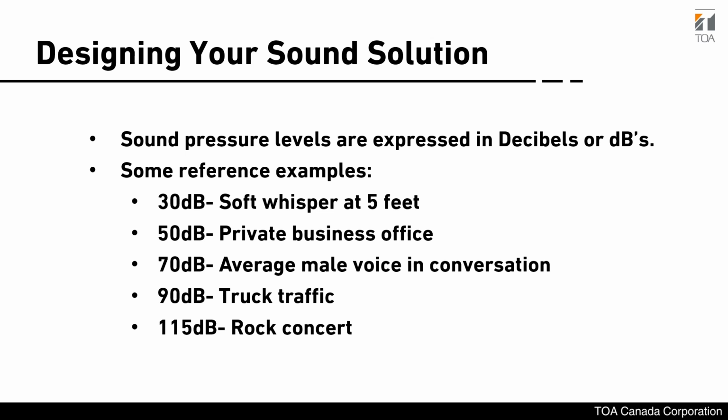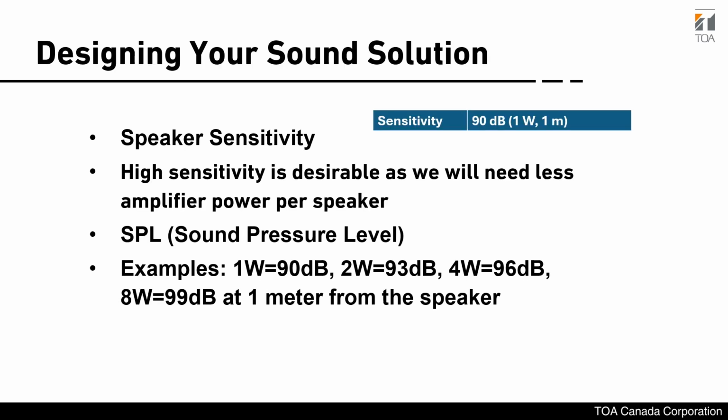Now let's talk about speaker sensitivity. This tells us how effectively a speaker produces sound. Most manufacturers, including TOA, measure sensitivity at 1 meter using 1 watt of power. A higher sensitivity means less amplifier power is needed per speaker.